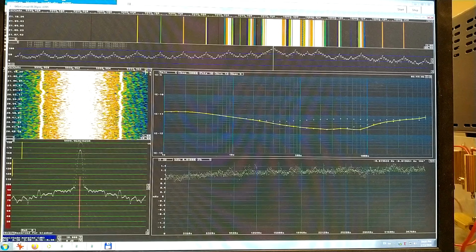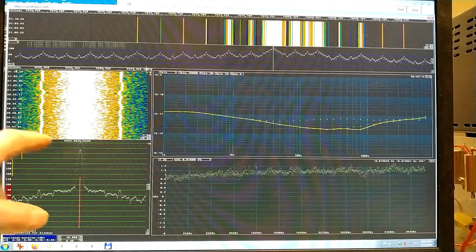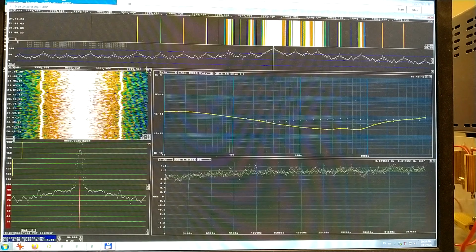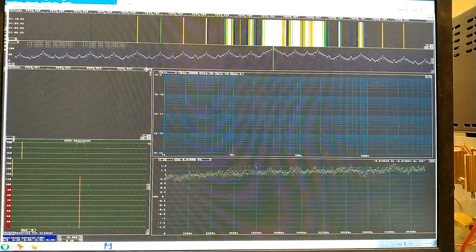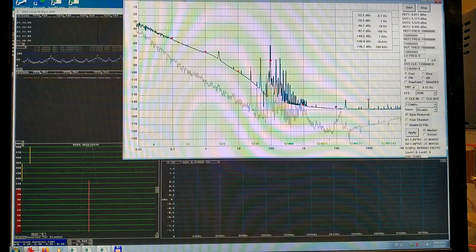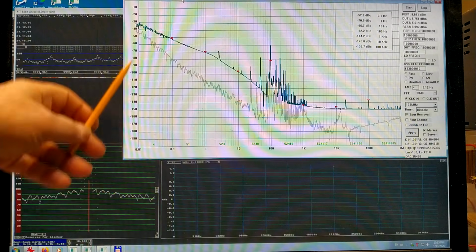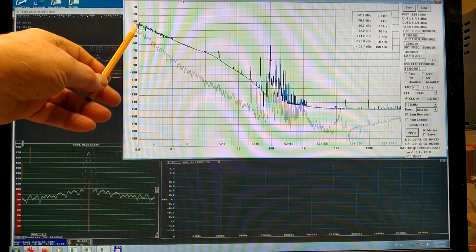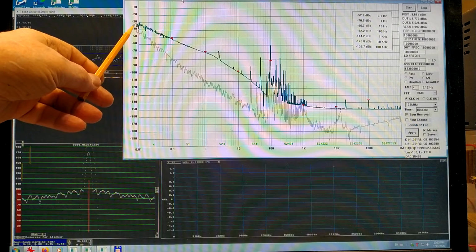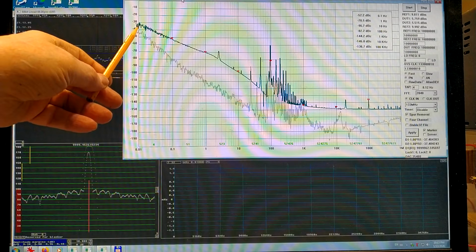And I can reduce it further by making a larger transform size in the baseband. It makes things run slower, of course, but it will reduce the noise that I will see on the carrier. The phase noise at 0.01 Hz is at minus 32 dBc per Hertz. And this is about 100 seconds then.